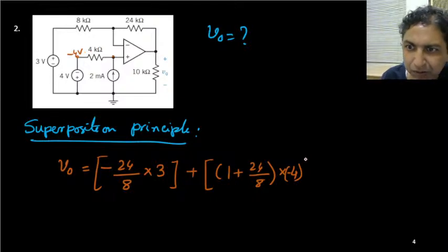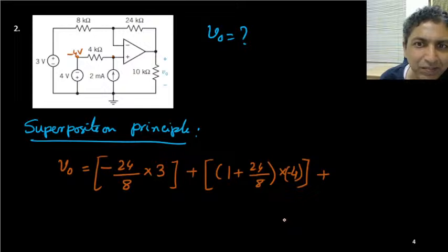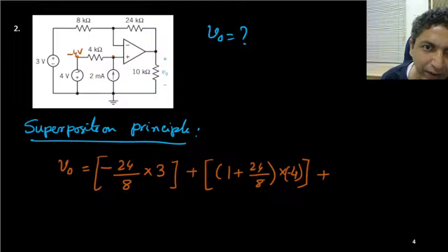Yes, good. And the last one, what is this? So 2 milliampere current is flowing. This is short circuit. So if it is not there, it is short circuit. Then what is the potential here? So that potential will be the supply potential at non-inverting terminal. Okay, so 2 into 4 means 8 volt. Am I correct? This will be 8 volt.